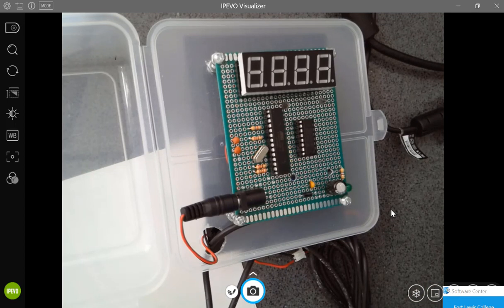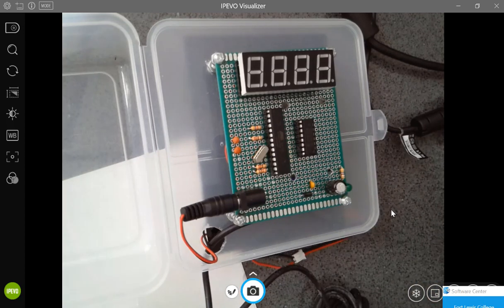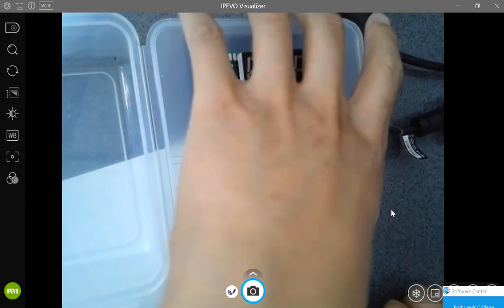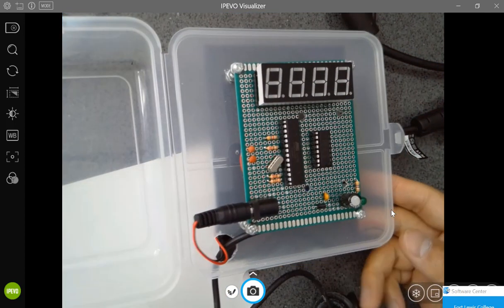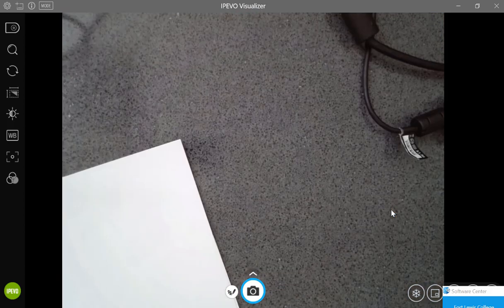You put all the temperature sensing code into the ISR, the interrupt service routine, triggered every 10 minutes. So it just keeps doing the display in the loop all the time, and after every 10 minutes, you trigger the ISR, do the temperature sensing, and then come back. Does that make sense? The temperature in the swimming pool is not changing every second, so you don't need to sense it in real time. That's one of the applications where you need interrupts in your design. Anyway, we're going to cover that on Wednesday next week.